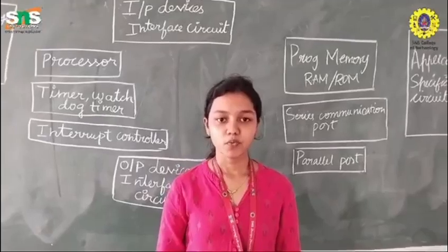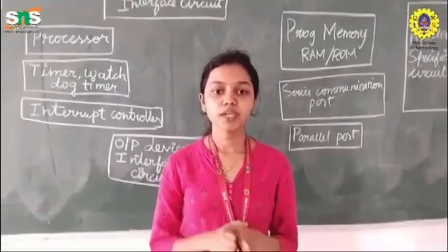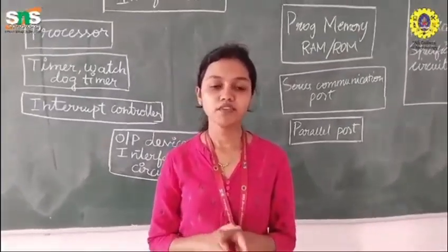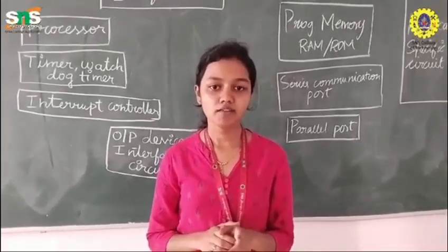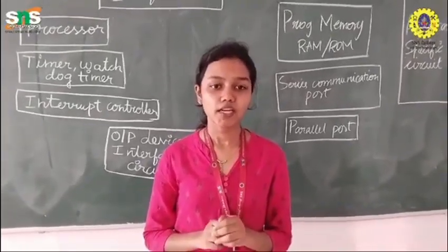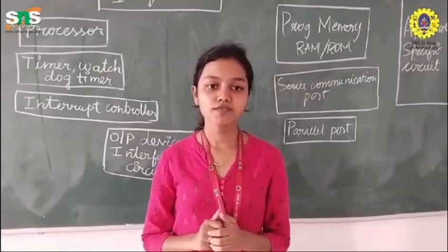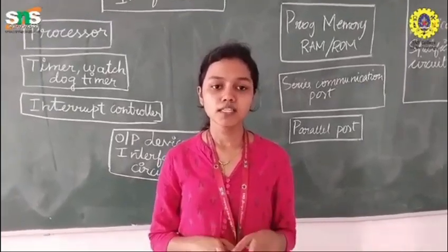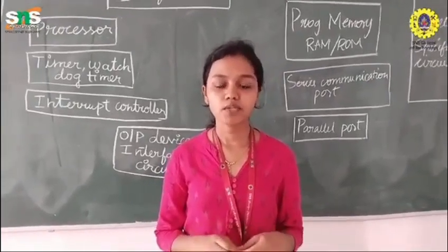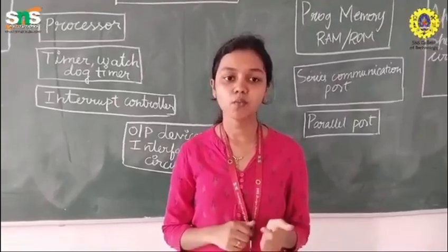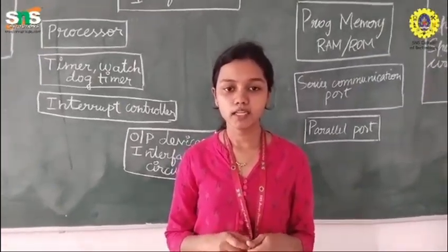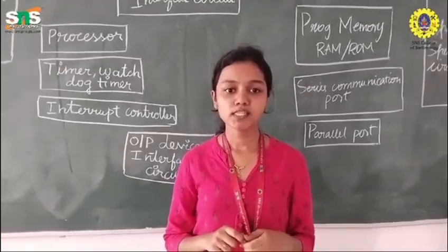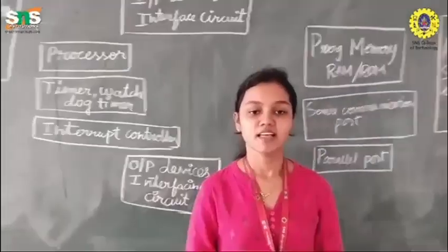Serial communication port. With the serial communication port, you can communicate with other embedded systems via this interface. In embedded systems, various communication interfaces are available including UART, USB, Ethernet, RS-485 and many more. A serial port is an interface for serial communication in which data is transferred one bit at a time. The serial port protocols UART, SPI, SCI and I2C are often used.